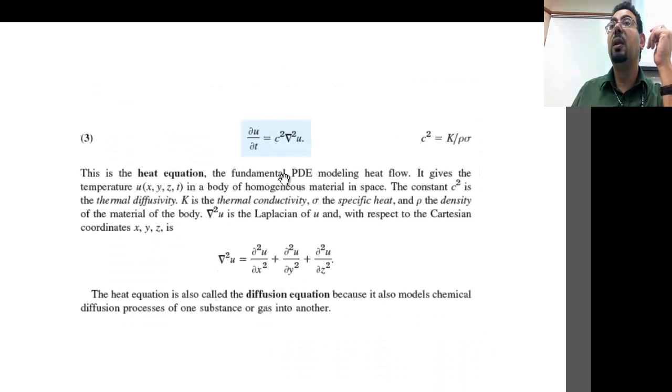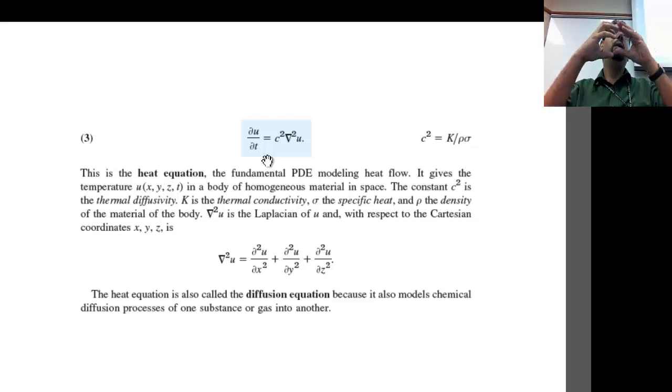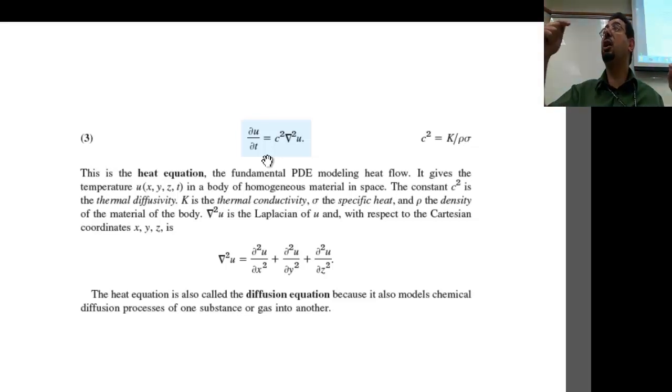And eventually when you take a certain body, a sphere or a rod, you can consider how much conduction is coming this way, how much conduction is going that way. The net conduction at the end of the day is going from this side minus this side, and it will get stored here. If you have Q by conduction coming in and not that much leaving, the difference between them gets stored in terms of internal energy. It will make this body hotter.